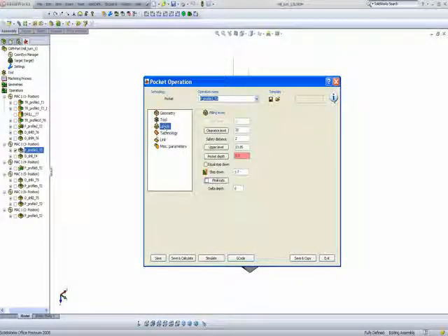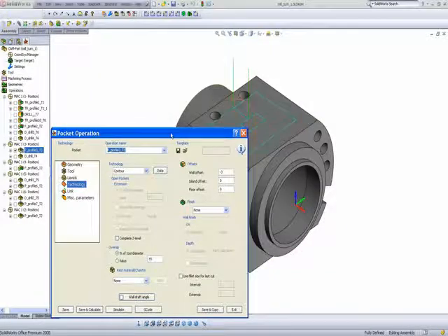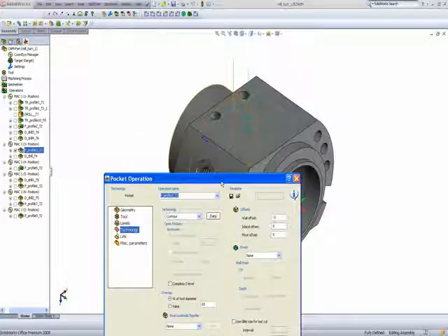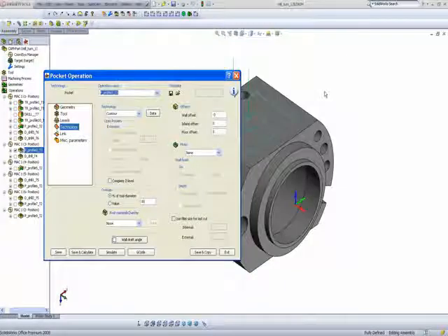In my levels, as you can see, let's go to my technology. And true, I could have actually done this using a face mill operation. But I'd like to show you also that within the pocket operation, we can also work on the system. I'm doing it in a normal profile operation, but what I've done is I've given the wall offset in the negative field, thereby forcing the tool to go past the boundaries of the part itself.